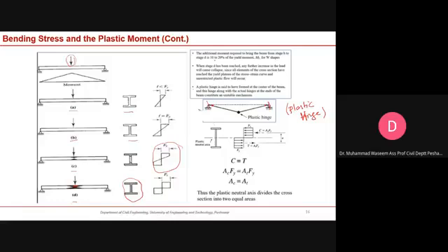One other thing you should note down is that in order to reach from state B, which is this one, where the stresses in the member are at yield, to stage D. Stage D is fully plastic. All the members have fully developed yield. For a wide flange section, MP is about 10% to 20% more than My. Once you have this type of state, you come here.